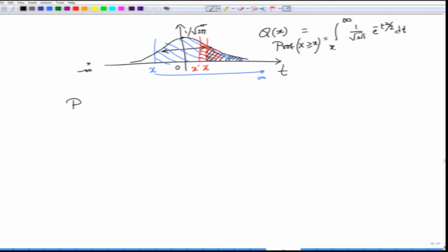So the probability of the receiver declaring 1 given that 0 was transmitted is given by the area under this probability density function, where you are going from the threshold current to infinity, e to the power minus, we had considered n0 here, so let us consider that n0. So n0 square divided by 2 sigma 0 square dn0.